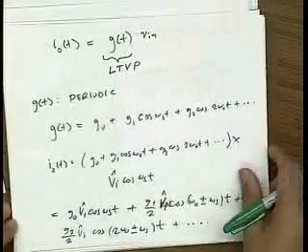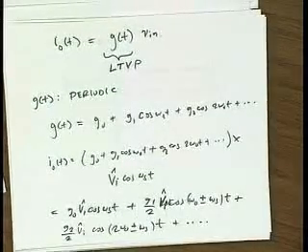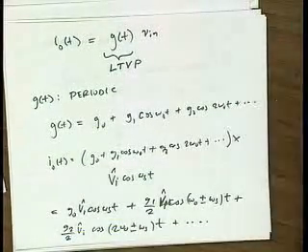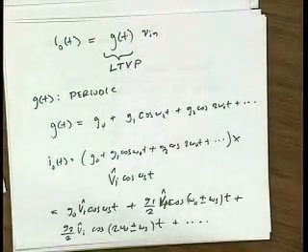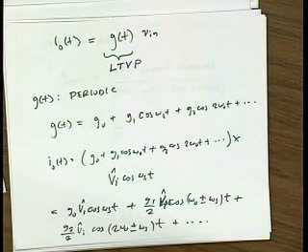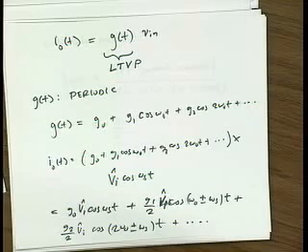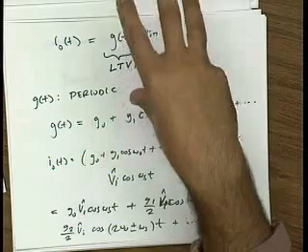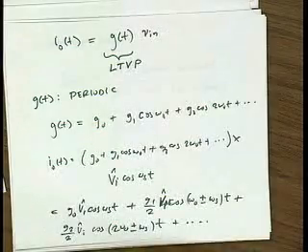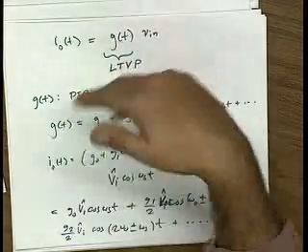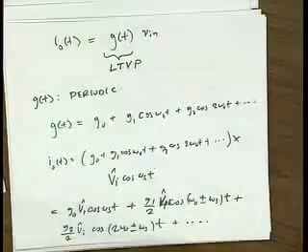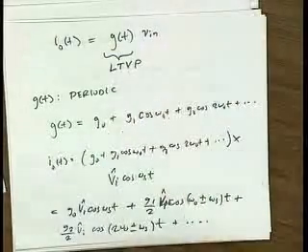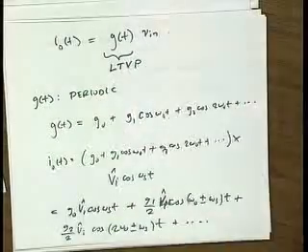I have a question. Yes. If the local oscillator signal is a perfect sinusoid, does this mean these harmonics, 2 omega naught, are generated because of the nonlinearity of the circuit? Yeah. Even if we assumed that the LO is a perfect sinusoid, we did that when we looked at the large signal behavior of a differential pair or a single transistor, and even there we get harmonics.